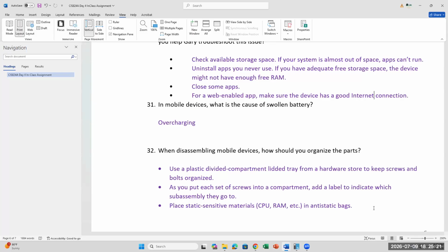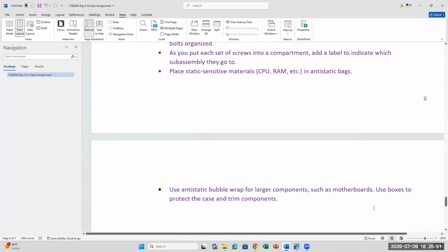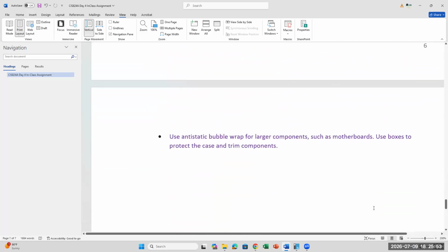Be creative. You should use an anti-static strap, or make sure that if it's anti-static, like CPU and RAM, it comes with these silver bags or the bags with the black stripes, right? Those are anti-static bags, so keep them in there. Before you touch the component, touch the bag, because it would de-static you. And touch metal. Get grounded.